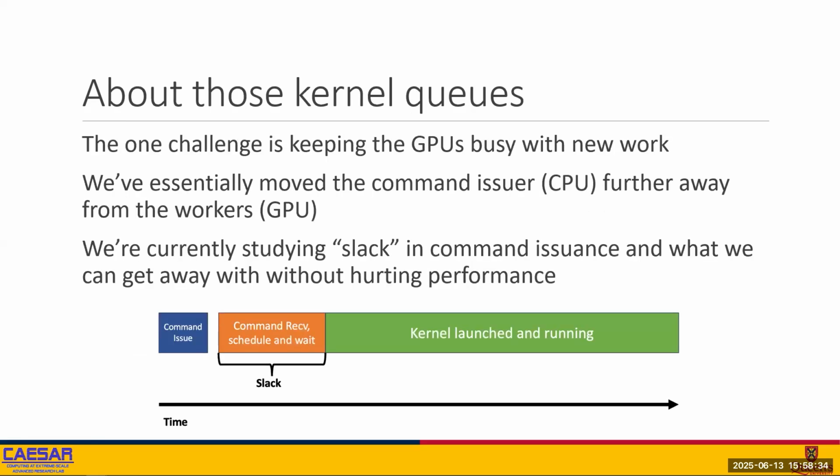So let's talk about that for a second. When you've got a GPU, what are you doing from the CPU side? There's two things that you're doing. You're sending data to it, and there's multiple different data sources you can get to the GPU from. But essentially, the one thing that the CPU does that no other component in the system does is send GPUs the commands. You tell it to run a kernel, you tell it to create a synchronization event. The CPU's sending commands, right? But the way that GPUs work and the scheduling that they do and the way that they build up their pipelines, GPUs basically are engines that you don't want to stop. You want to keep feeding them. Once you start them, you keep feeding them. They're hungry for data and you don't ever want them to stop. They're fast that way. What it means is that we actually end up sending commands about new kernels and things that we're doing next in our streams early on, where they actually get sat in queues for a little while before they actually get run, right?